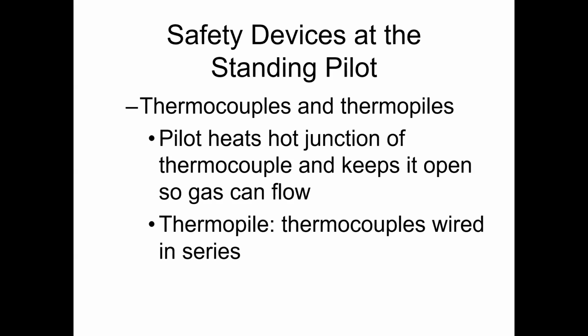This thermocouple buildup with the soot and everything like that is super easy to take care of. Everyone here, I hope listening, has at one point in their life scrubbed some dishes and come across a really nasty grease spot or something that was just cooked on, burnt into it. You probably use something like a Brillo pad or the scrubby side of a sponge to clean that off. It's the same exact thing we're going to use to clean our thermocouples, to scrub off that soot. And that's all you've got to do. You just scrub it off a little bit, and it's amazing how little it takes to clean off a thermocouple and make a huge difference.